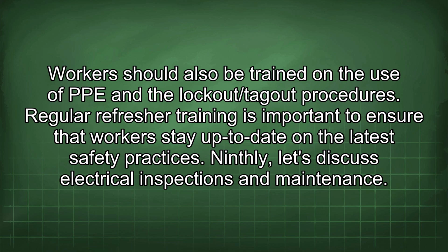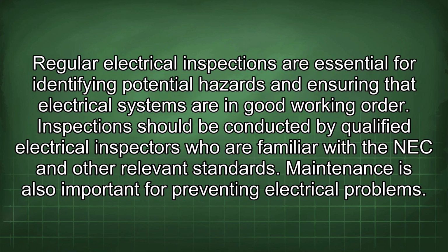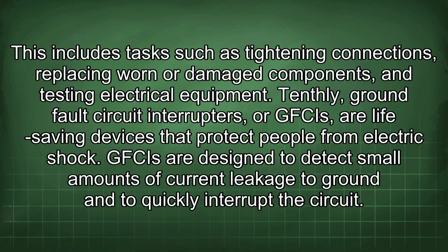Ninthly, let's discuss electrical inspections and maintenance. Regular electrical inspections are essential for identifying potential hazards and ensuring that electrical systems are in good working order. Inspections should be conducted by qualified electrical inspectors who are familiar with the NEC and other relevant standards. Maintenance is also important for preventing electrical problems. This includes tasks such as tightening connections, replacing worn or damaged components, and testing electrical equipment.